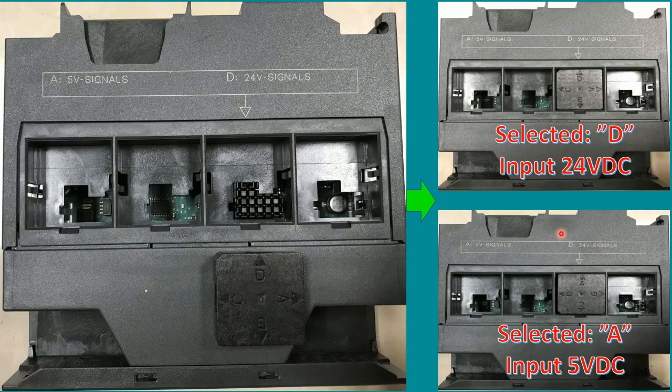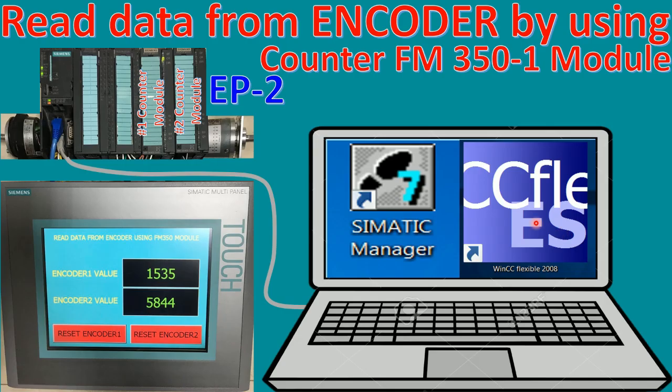24 volt DC. Okay, so today we will use two encoders and use two modules of high-speed counter to read the data and show on the HMI, yes. And I will use the Simatic Manager and WinCC flexible to create the new project and HMI, yes.